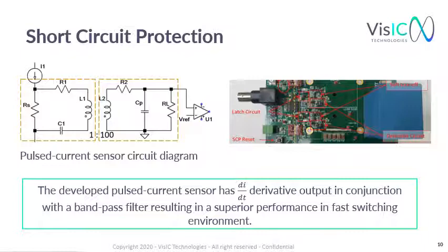On the right, you can see the half-bridge evaluation board on which this circuit was tested. The small transformer and logic circuits take minimal PCB space and can be easily implemented. Once this scheme detects abnormal current slew rates, the GaN device is safely turned off in a multi-gate voltage step approach, in order to avoid high drain voltage spikes. Additional information can be found in a paper by VisIC at ECCE 2020 titled Short Circuit Protection Circuit for Automotive Motor Inverter Applications based on GaN transistors.